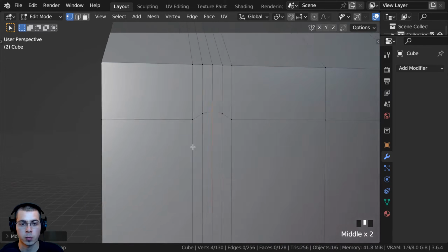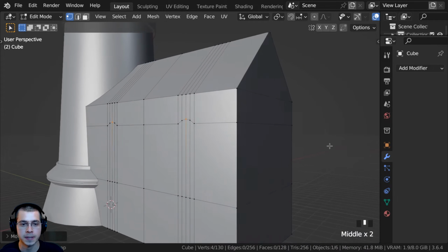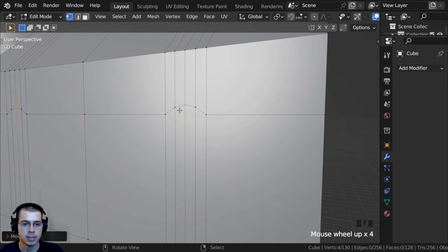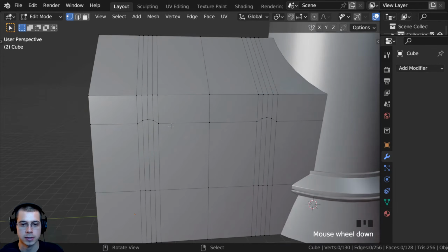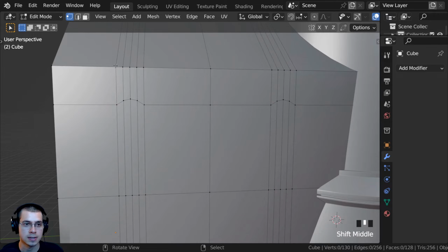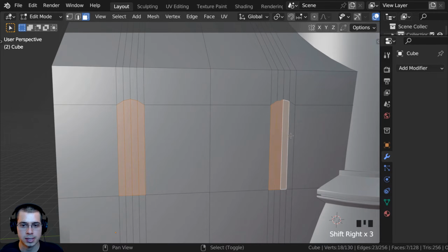And because I did this in wireframe view, if I go over to the other side of the lighthouse, the back here, you can see it's done the same thing because I did it in wireframe, so it selected the back vertices. So I can now just delete these faces. So I'll go here to the face select. I'm going to click and drag to box select these, and then hold down the shift key, and we're just going to select those 4.